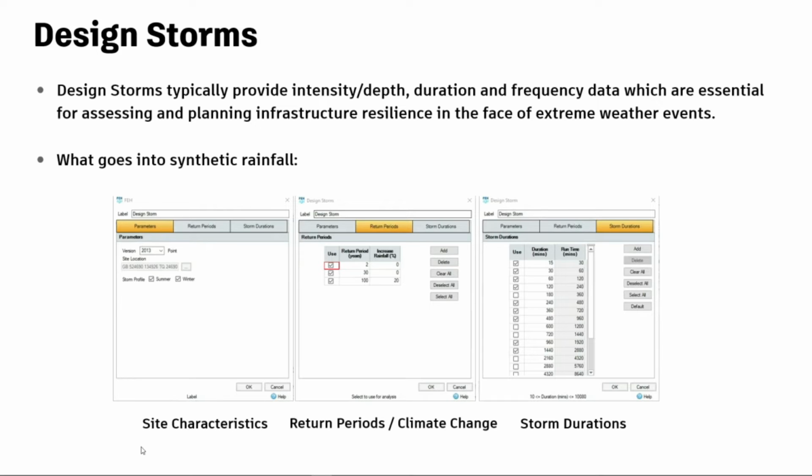Additionally, it is also just as important to consider climate change in our storms. Climate change adjustments are predictions of anticipated change for peak rainfall intensity. To increase resilience to flooding, you should make allowances for climate change in your drainage systems by adding a percentage value to the return period. For example, in Bristol, for the 100-year storm event, a climate change value of 40% is required.